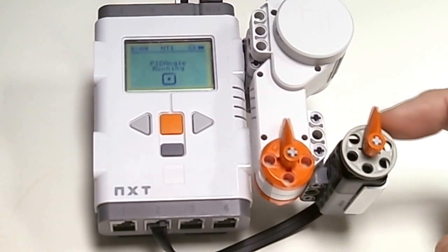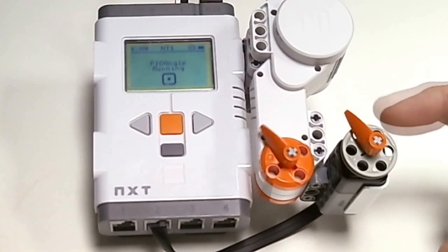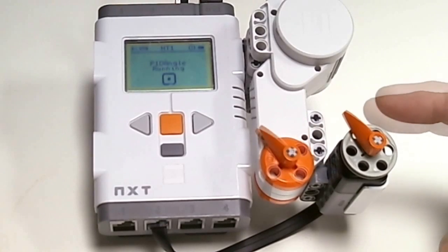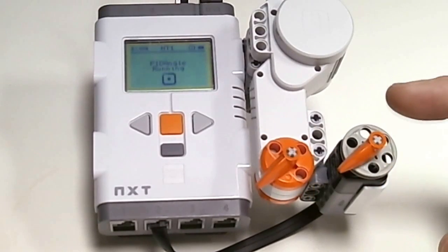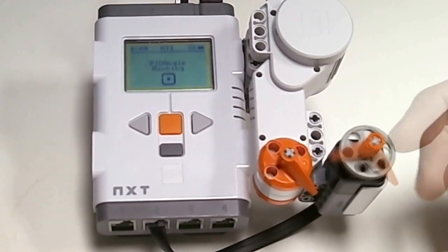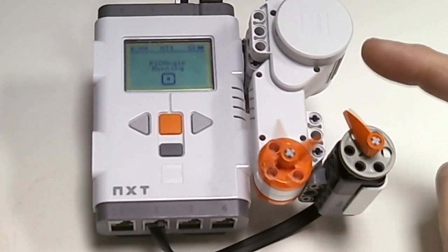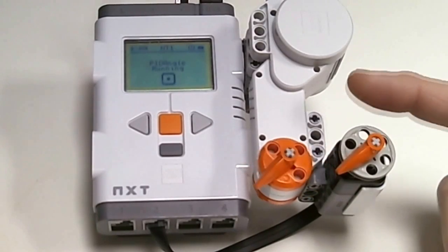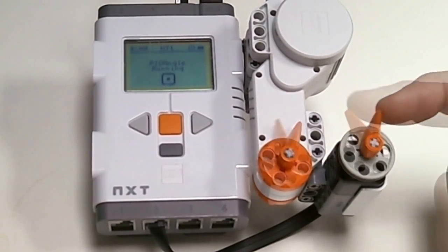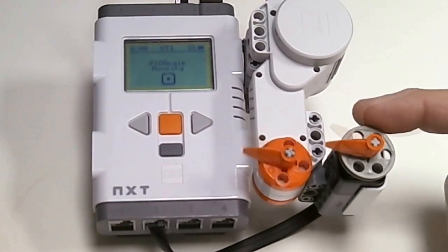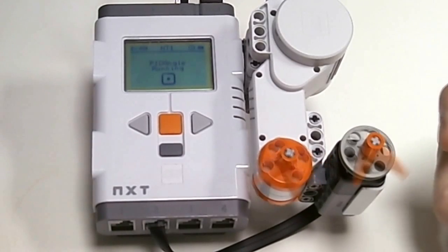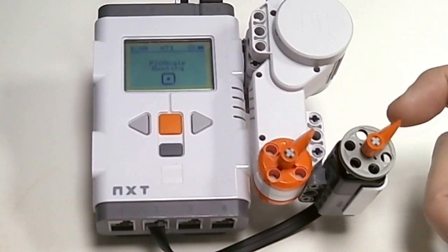Notice that in the loop, it's very quickly reading the angle sensor, the accumulated angle, and then it passes that directly to the PID block, which makes the motor get there as quickly as it can to whatever position you're setting the set point to, with very little overshoot, and it's very powerful. I'm almost putting no effort into the angle sensor, but the motor is using up to 100 power. So if you had something heavy on there, no problem. It would just go there.